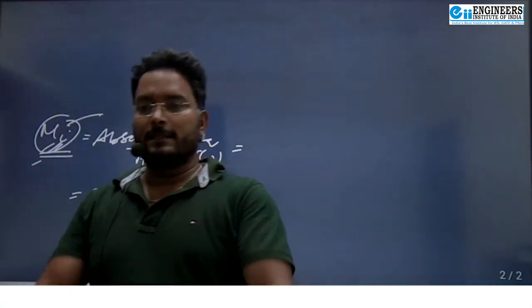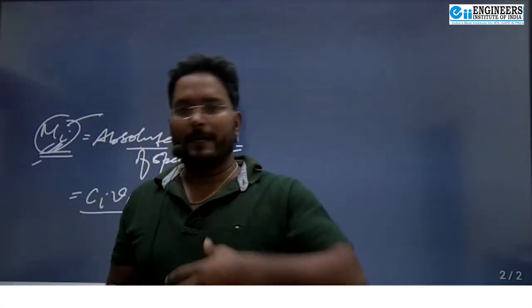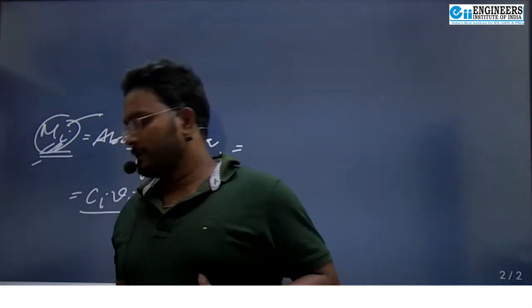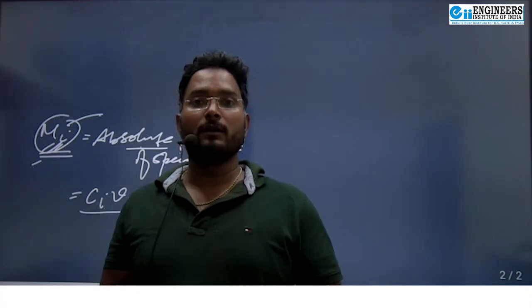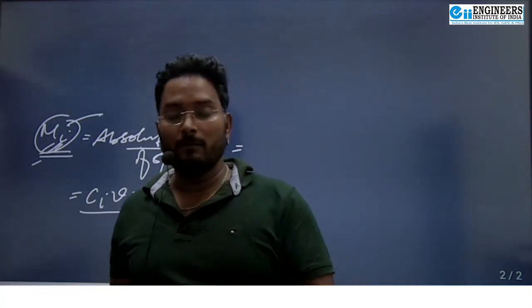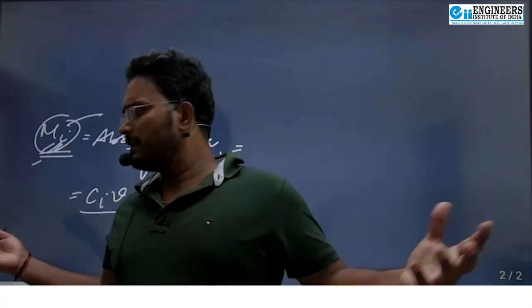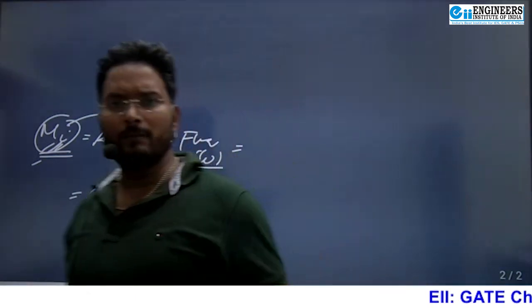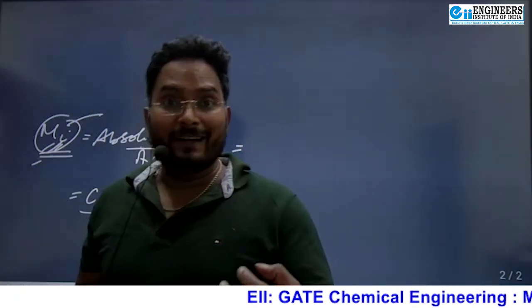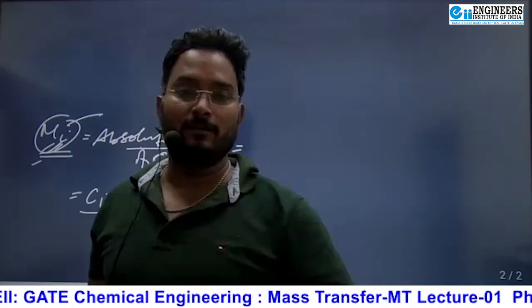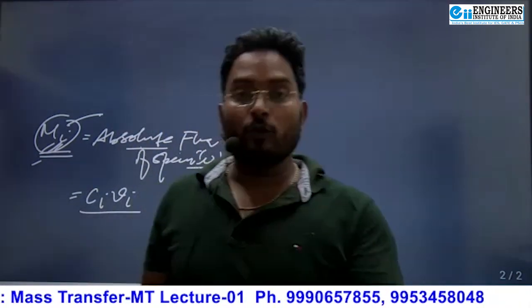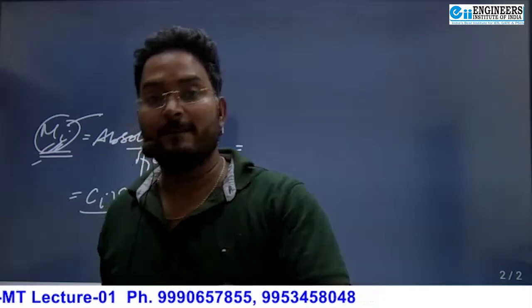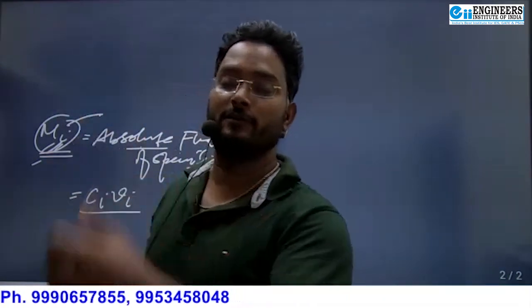Suppose I have thermal energy, because every molecule moves randomly at the microscopic level because of its thermal energy. So I have thermal energy, I am energetic, I will move here and there. It is my own characteristic feature. Any transfer of the species by its own characteristic feature is defined by Ji, called Fick's law of diffusion, called molecular diffusion.